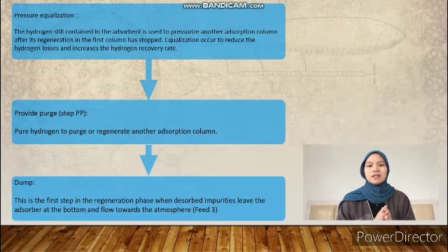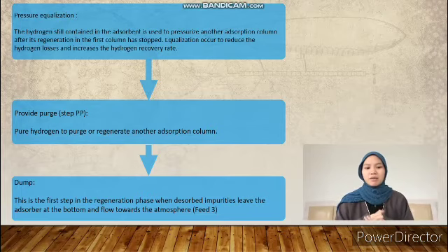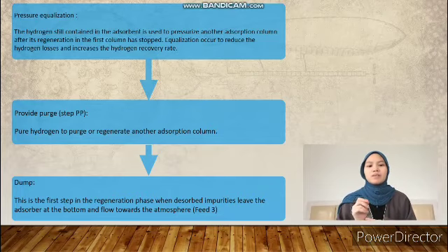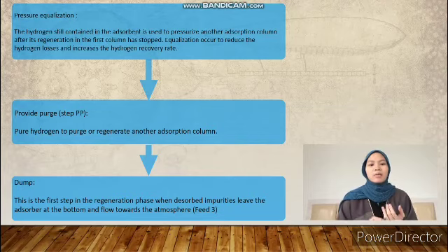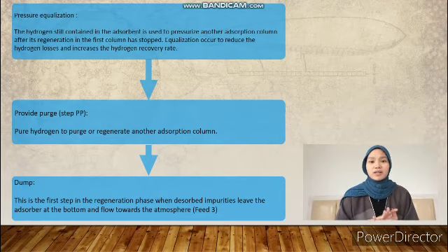Lastly is the desorption or regeneration process. In the PSA process, gas is compressed to a pressure between 4 to 10 bar and is fed to a column where it is put in contact with zeolite that will selectively retain CO2. The adsorbent has a characteristic of porous solid, normally with high surface area.